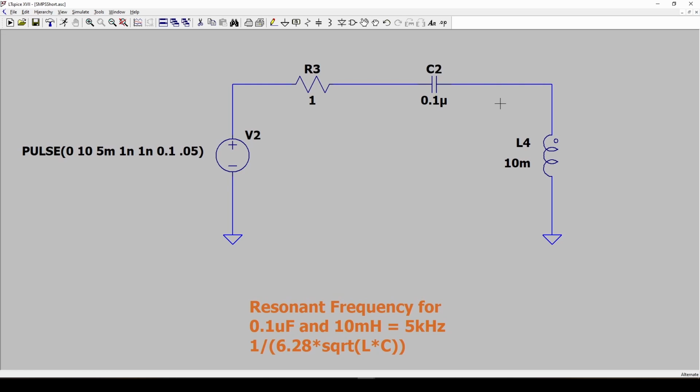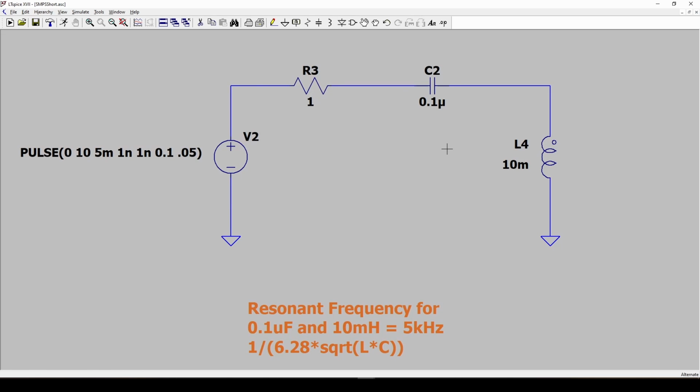And you may be familiar with this. It is what's called an LC oscillator. And the L is the inductance, the C is the capacitance. And in fact, this is an RLC oscillator because it's got a resistor with the capacitor and the inductor. And the way this works is very much like in the real world. If you ring a bell, you take a hammer and hit a bell, what happens? Well, it rings, it oscillates, and over time it decays, and at some point the bell stops ringing, right? It dies out. And that's exactly what this does, but it's in an electrical system instead of a mechanical system.